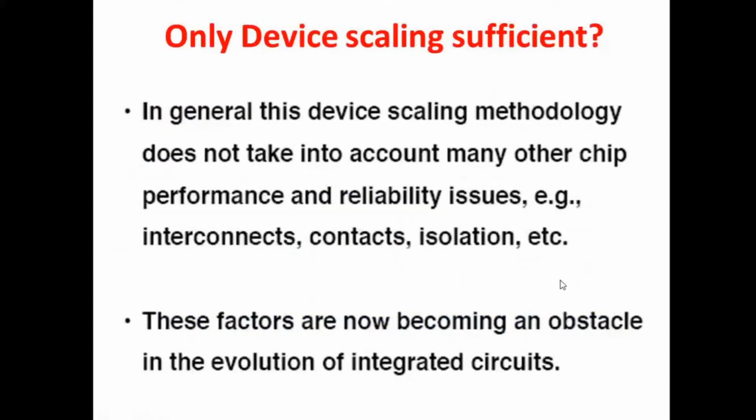Even scaling the device, that is the MOSFET, but scaling MOSFET, is it sufficient? Along with the MOSFET, we also need to scale the interconnects, the contacts, the isolation, etc. These are the factors which are now dominating the evolution of integrated circuits.